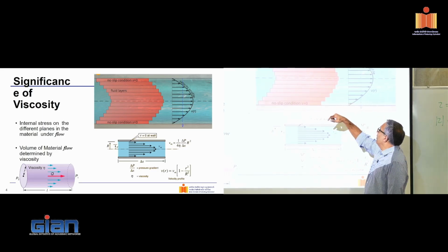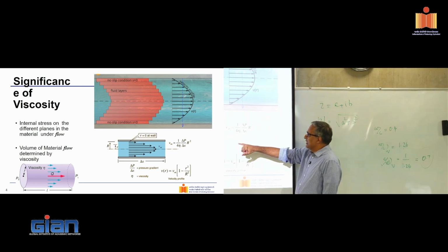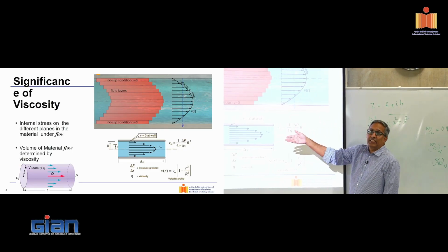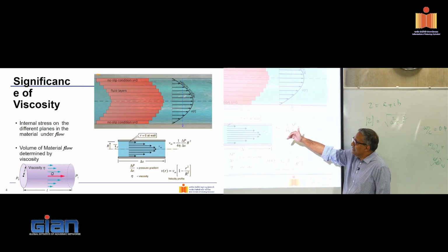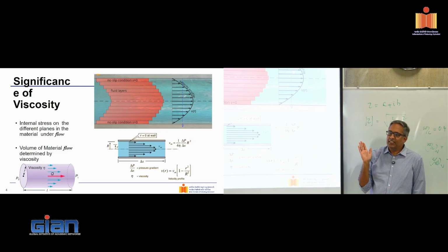The velocity profile builds up and you get a velocity profile where you have the highest velocity in the middle. And what determines this is basically the viscosity of the liquid. You basically create a shear stress across the height of the pipe. We are all used to handling this, right? We've done this in our first year, second year BTech curricula.